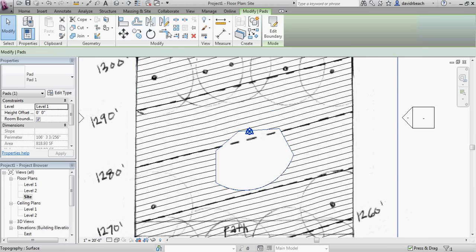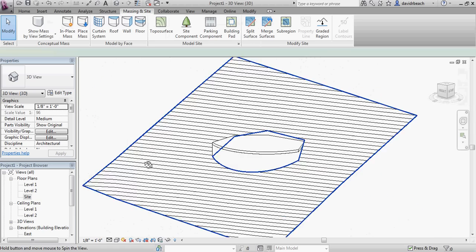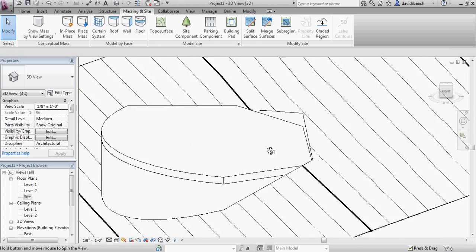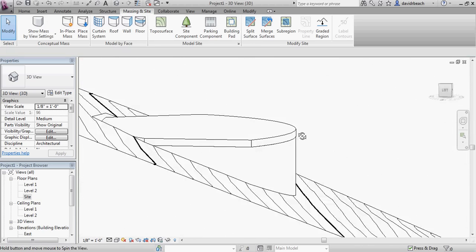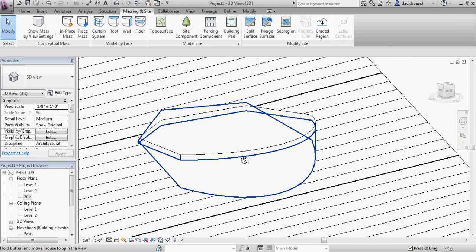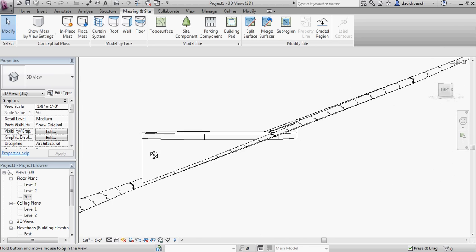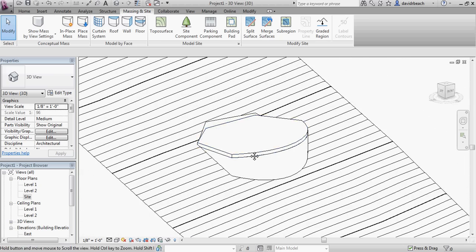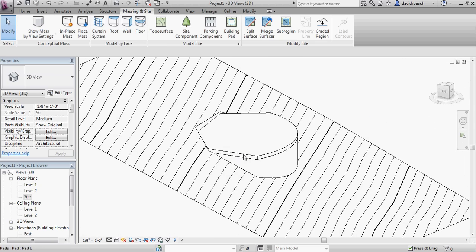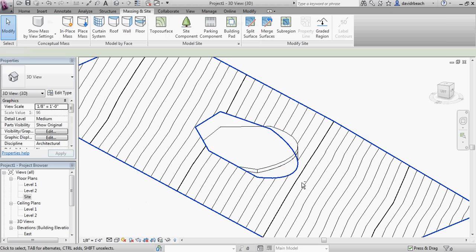So when I finish the building pad, you can see that it's actually building up that front edge, and it's digging in to that back edge a little bit. So let's say, for instance, that I really want that to be split more 50-50. That I really want the building pad to be sort of pushed down into this back edge, not be quite so tall on this front edge. So to do that, I have a couple of options. I could simply select my building pad elevation and just say, -4, and pull that down.